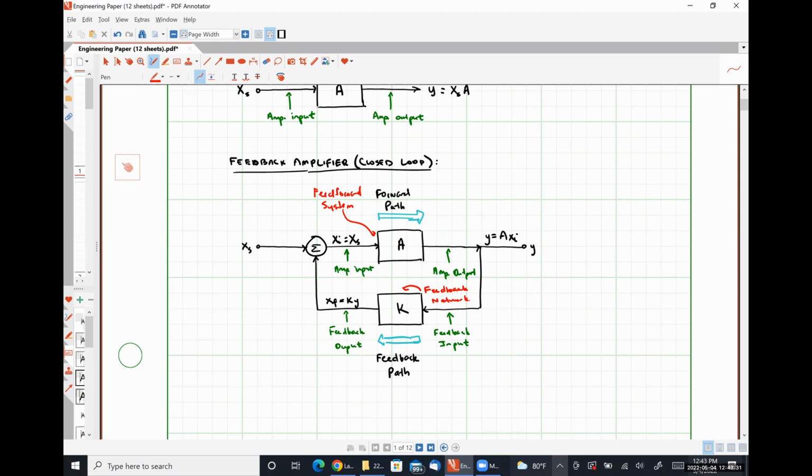All right. So we've come back around, we've completed our loop, and we're back around at the mixer. So let's talk about that guy. Okay. What it does is it adds our source signal XS, and it combines that with our feedback signal so that we're going to have XS plus or minus XF. Okay. If the sign on this combination is positive, we get positive feedback. If the sign on it is negative, we have negative feedback.